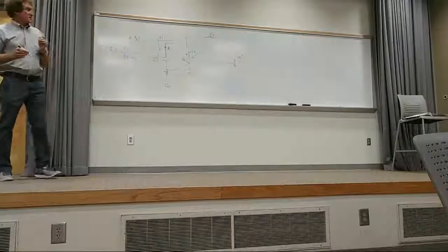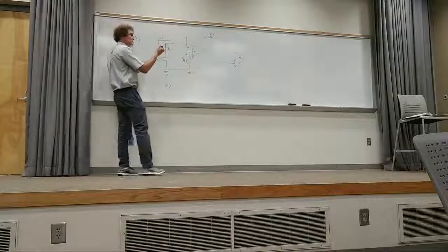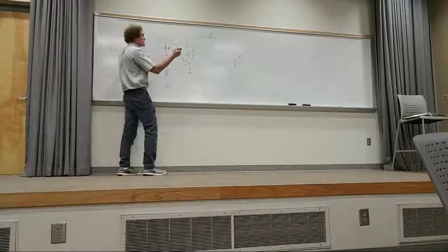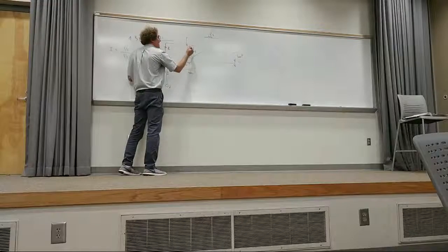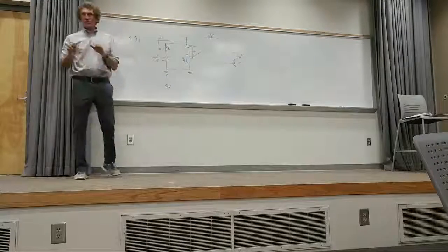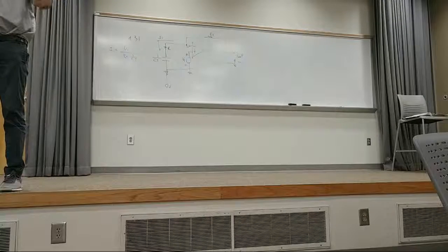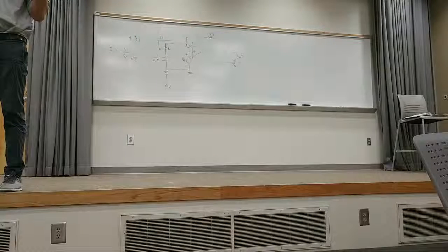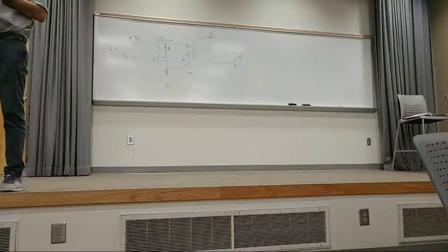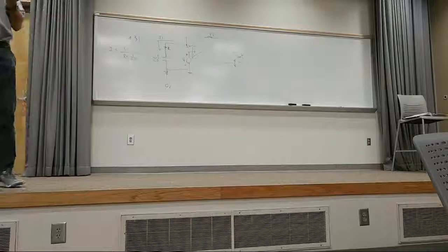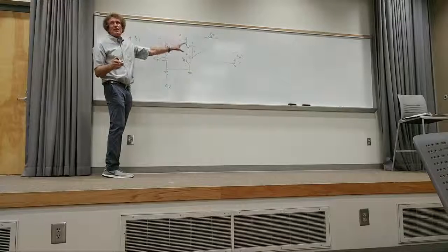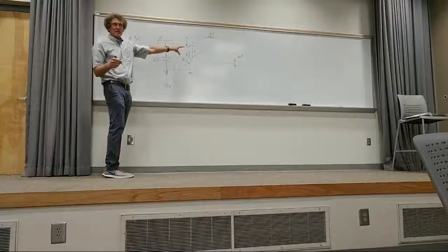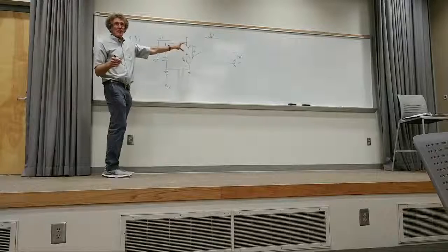All right. Now, if that's the case, go back here. It's purely deductive reasoning. There's nothing tricky about this. If all this current I1 is coming this way, how much current leaves the negative terminal? None, right? No current in or out of the differential inputs, right? That's critical. Do y'all follow me? I know you're saying, how can that be? It's done by the electronics. It's an active thing that has maybe 1,000 to 10,000 transistors creating this effect, all right? We're just showing you the block diagram.